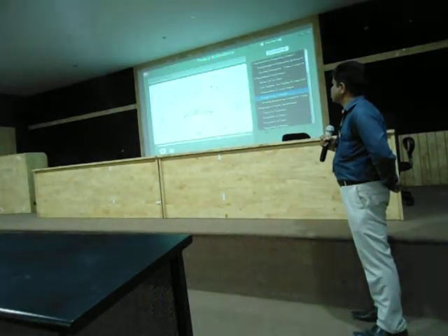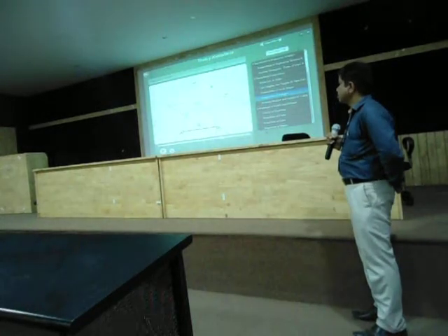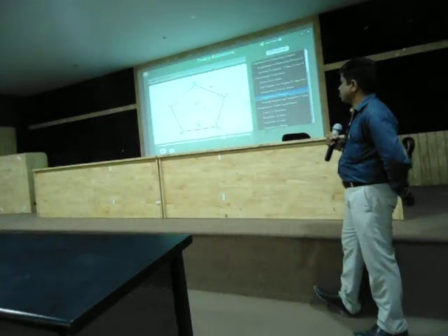After that, with E and R as centers and AB as radius, draw two arcs intersecting each other at point Q. Finally, let's draw lines connecting these points to complete the pentagon.